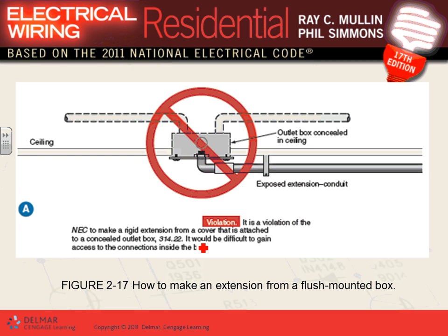So this is FYI. When we do transitions between wiring methods, I don't know how many of you guys with us are done with that. I don't think you go over more than probably 10 wiring methods, from MC to NM cable to AC cable to rigid conduit, EMT, PVC. That's what we do with you, close to 10 of them that we actually make you work with. We might talk about others. There are, like I said, 50 some wiring methods in an NEC code book, and different ways of transferring from MC cable into a PVC conduit or rigid into an EMT with the different fittings, and that's where a good electrician becomes better than good, an excellent electrician. The people who know it have experience with it.